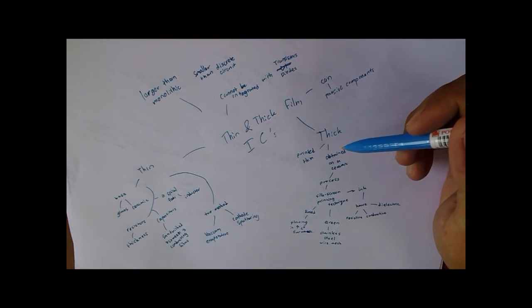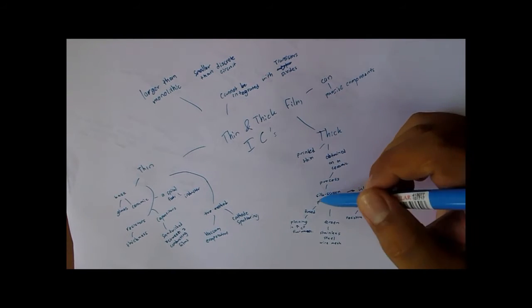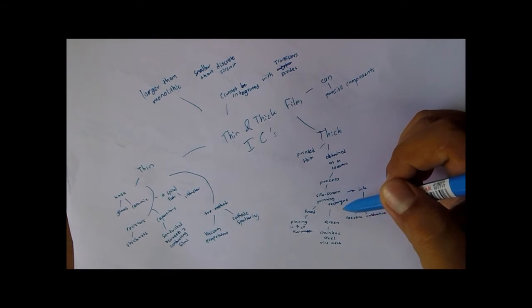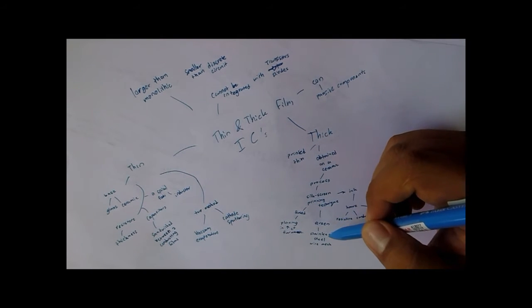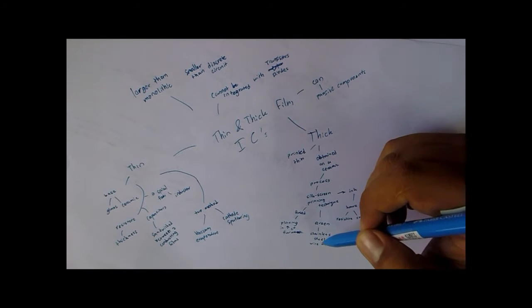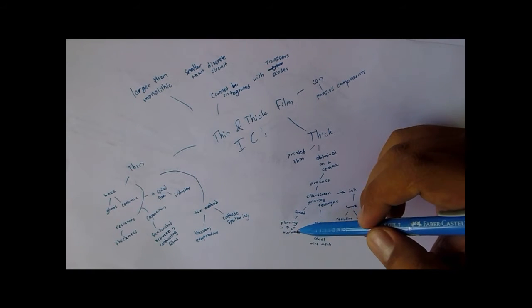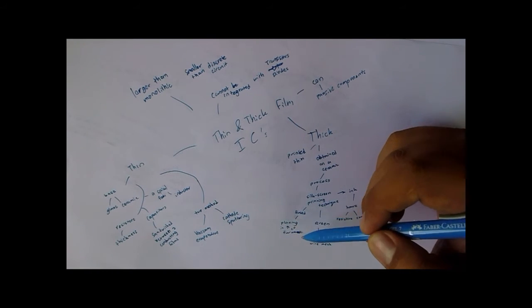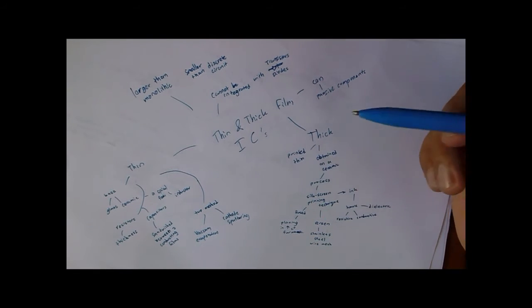The next one is thick film ICs, which are commonly called printed circuits, obtained on a ceramic substrate by using a manufacturing process called silk screen printing technique. The ink is usually a material that has resistive, conductive, or dielectric properties. The screens are made of fine stainless steel wire mesh. The films are fused to the substrate after printing by placing them in a high temperature furnace.